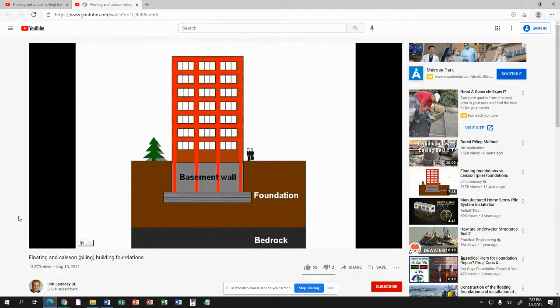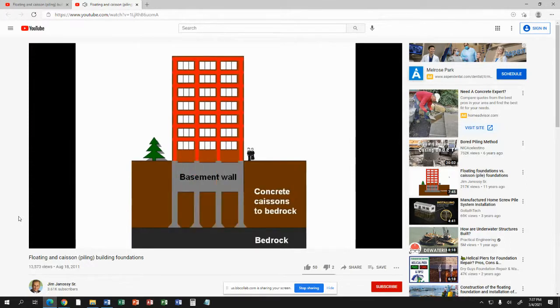It's not about to sink unless we have a major earthquake, and then it's all up for grabs. So the bedrock is where tall buildings have to be anchored. The taller they went, the heavier they got, and the less stable they would become if you tried to float them, as this building indicates. So here's what was done. Around 1900, they were experimenting with this. It actually got perfected into the 1920s as buildings reached even higher than 18 stories.